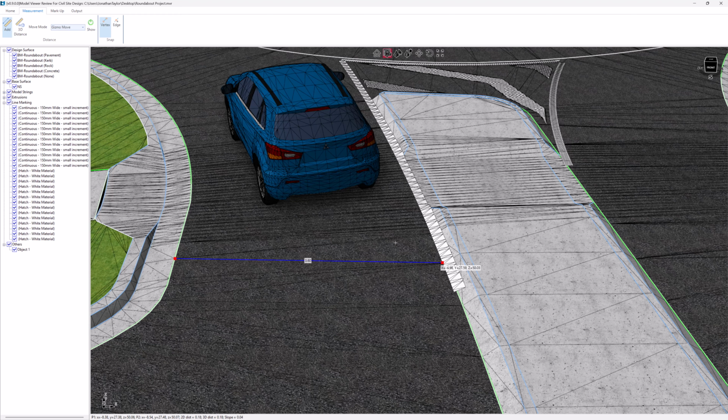And if I snap to the other end here, you'll see that I get that distance being applied along the edge. Now if I wanted to apply that in a similar fashion, but this time find maybe the middle point of a triangle over here, I could run that command again, click on Add, click near the end of the triangle, and then use the edge method to ensure by turning off vertex and snapping up onto the edge. You can easily turn the annotation on and off by clicking Show and Hide. If at any point you want to remove the annotation, you can just press Escape on your keyboard, left click on one of the blue lines, and hit the Delete key to remove the label annotation.